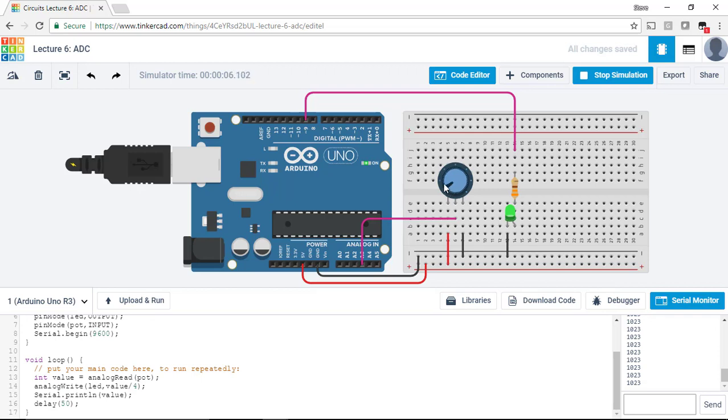Now let's translate that wiper position slowly back. We should see the LED dimming as the voltage drop is reduced. And at some point, the wiper position will be connected to ground. Therefore, there's no voltage drop between the wiper position and ground. You see in my serial monitor, my analogRead has decreased to 0, and the corresponding LED brightness has decreased basically to the off position for the LED.